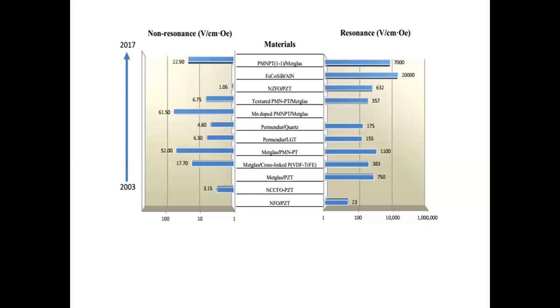At that time, the piezoelectric material in the composite vibrates with maximum amplitude, so very high voltage is developed across the material. Because of that, at resonance, very high values of ME coefficients are obtained.